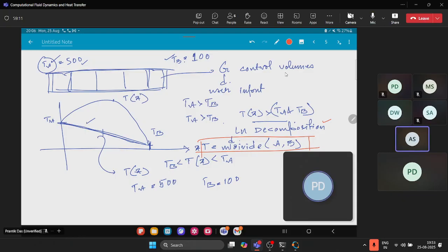For discretization, for a small system, LU decomposition is okay, right? But if we have a large system, meaning many equations, then maybe an iterative method has to be employed. That can be done. Then you have to declare the matrix to be a sparse one, and then you can use other kinds of methods also. But as of now, I'm using this ML divide function since we are taking very few control volumes or cells within that domain itself. Maybe 5, 10, 15. So it doesn't matter.